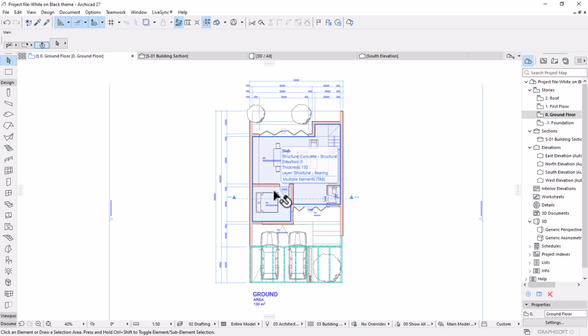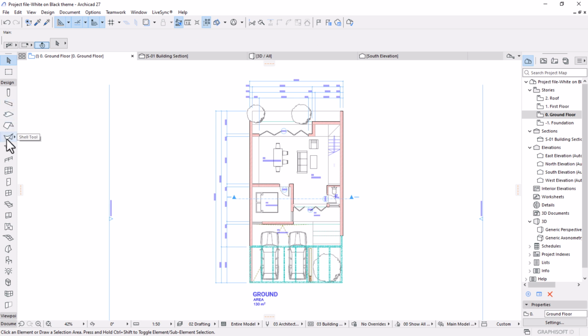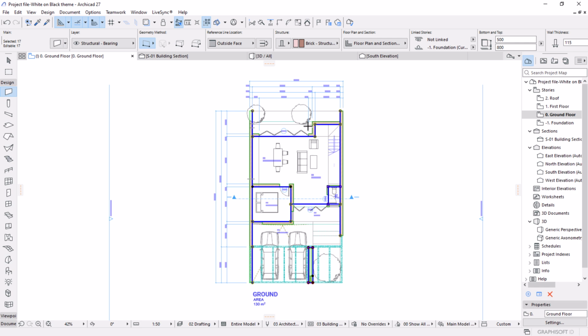For example, I can select everything like that. Obviously it will pick one of the elements, but you have to select elements one by one. So let's start with the walls. For example, I'll pick the, where is my walls, the wall 2. Yeah, there we go, and then hit Control A to select all the walls. What you need to do here is to change the cover fill or the hatch fill for the wall, and then change as well the line type pen for the walls.